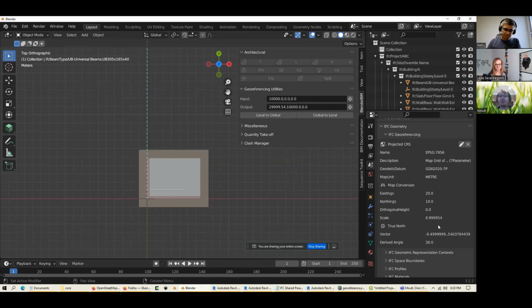The difference between the two is that the site survey is in eastings and northings, and the site drawing has the false origin already applied and it's already rotated to project north and has any scale already done to it. So that way it's all set up already for you. And if you link that into Revit, it will look perfect. Amazing. Does that kind of make sense? The kind of 10 things you've got to ask your surveyor?